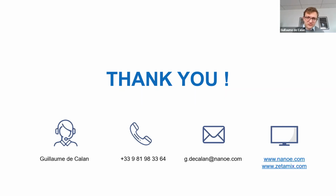How much is the precision and resolution of this technique? I guess, again, we're talking about FDM. I didn't specify that, I should have, but in most of the MIM-based technologies, precision is going to be limited more by the sintering and the shrinkage than by the actual printing. Of course, binder jet is a little bit more precise than FDM, but not that much, because anyway we're going to have to sinter, and sintering is going to play havoc with precision. That's really the difficulty.